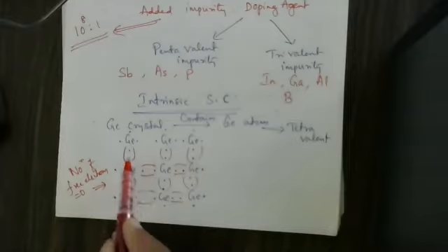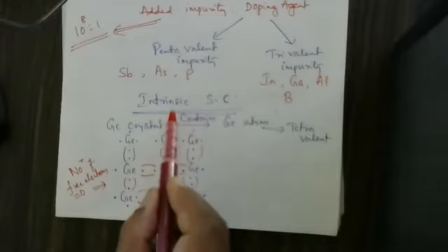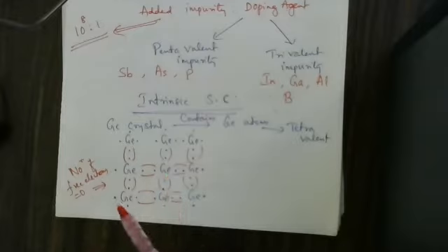So this is the germanium crystal. The germanium crystal is containing 4 valence electrons. All the 4 valence electrons are involved in the 4 covalent bonds. Hence, the number of free electrons available in an intrinsic semiconductor is equal to 0. If it is equal to 0 here, it cannot conduct. It cannot conduct. At what temperature? That is also important here now: at 0 Kelvin.